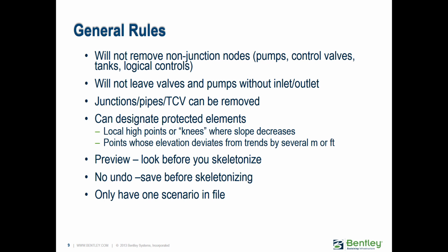So some general rules for skeletonizing. Again, these are the rules for Skelebrator. It won't remove nodes that are significant, like pumps, control valves, tanks. It'll remove junctions if it needs to, but other things like pumps, controls, tanks, those will always be kept, and it won't leave things like that at a dead end. So you won't end up with a pump at a dead end, because a pump needs to have a suction and a discharge pipe.